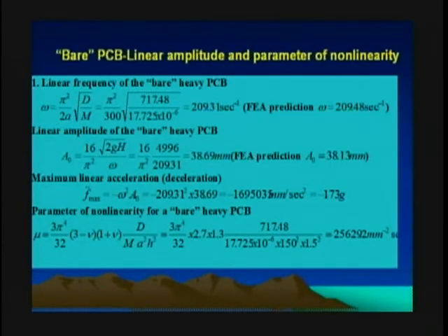Then we calculated the linear frequency of the bare, heavy printed circuit board. What we call bare, that we don't have concentrated masses, but we call it heavy when the concentrated masses are spread out around the board surface, and therefore, yes, the board doesn't carry concentrated masses, but its weight was increased based on these concentrated masses. We call it bare because it doesn't have concentrated masses, but heavy because the masses were distributed.